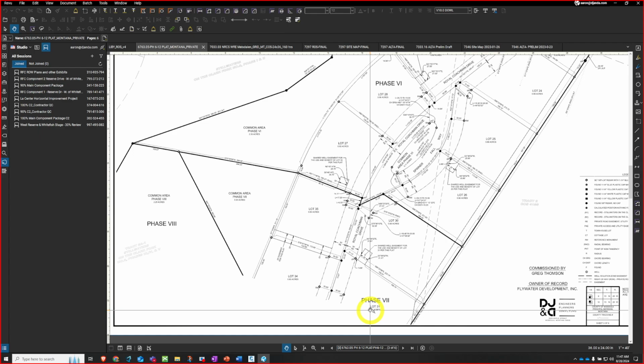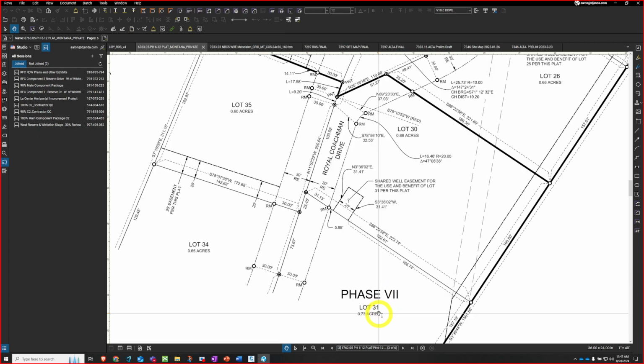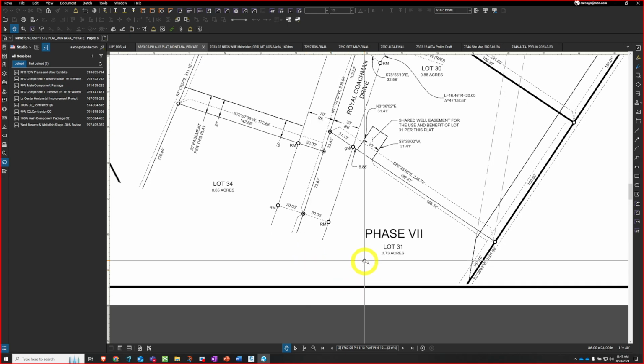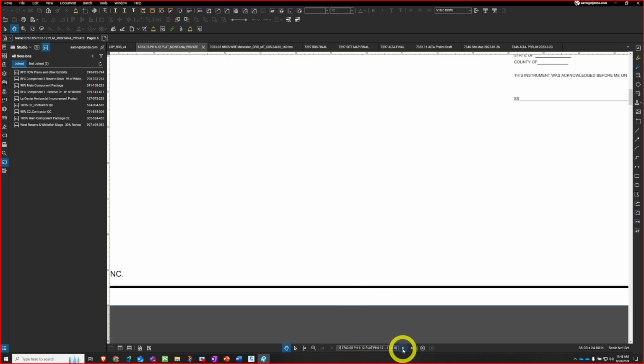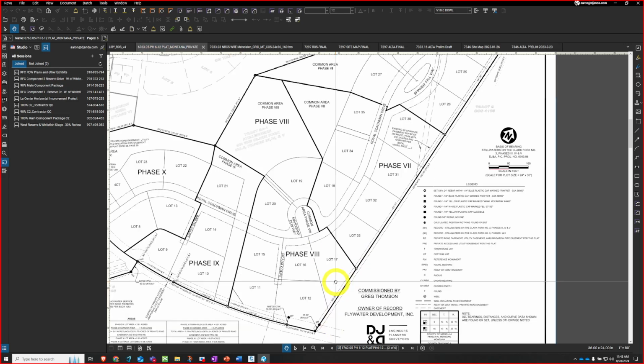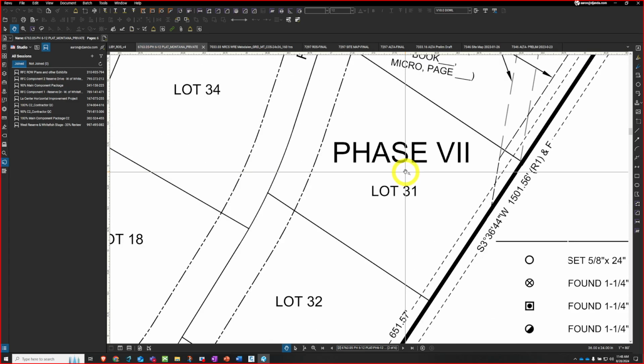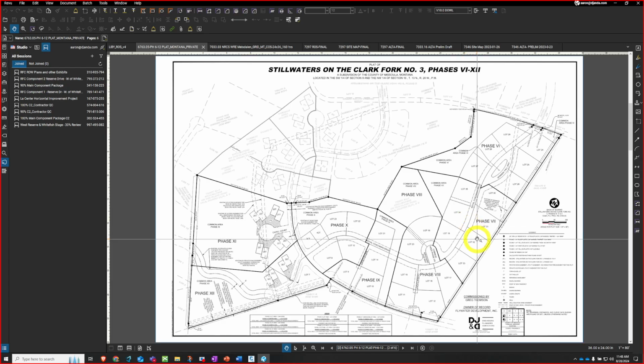Once you get good at using them, let's say I had this annotation here that was in the right spot, but on another sheet at a different scale, it was over here in the wrong spot. That's literally the same annotation, but it scales up for this scale. I can put it completely spatially in a different spot than on the other sheet, and it's all on the same layer. That's some of the power of using annotative.